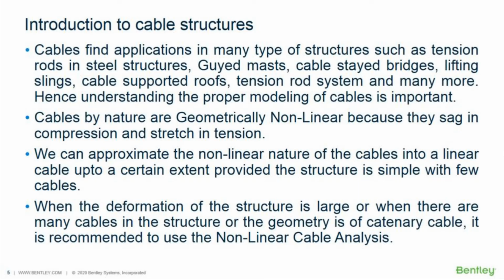largely we can summarize where we can find the application of nonlinear cable analysis. When the deformation of the structure is large, or when there are many cables in the structure, or when the geometry is of a catenary cable. A catenary cable is a curved profile of a cable. When a cable, for example a horizontal cable, sags due to self-weight, you can see the curved profile of the cable. So that needs this nonlinear cable analysis.